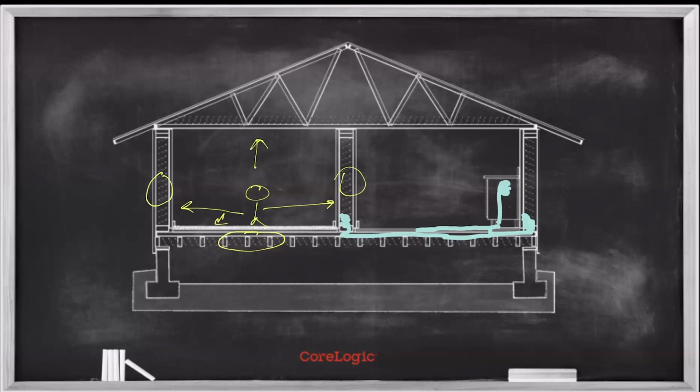And what I'm stressing there is that if you checked it for a reason, right? You checked it because there was a chance it could have been wet. You found out that it wasn't. Wonderful. Document that, right? There should never be an instance where we've inspected an assembly and then a component in that assembly during that investigation and not documented something and not committed that to the record in some way. Because if I could reasonably argue it could have been wet, so can somebody else 6 months from now when they do a remodel and open that wall cavity and find a bunch of microbial growth, right?